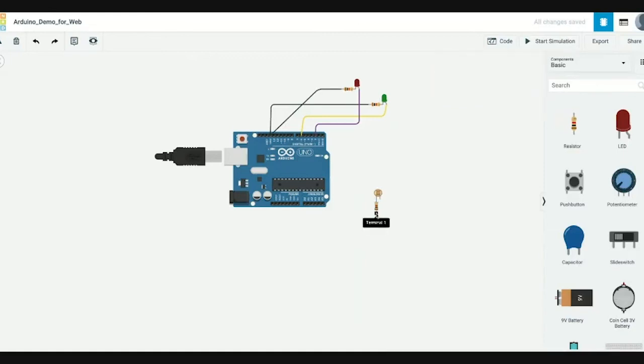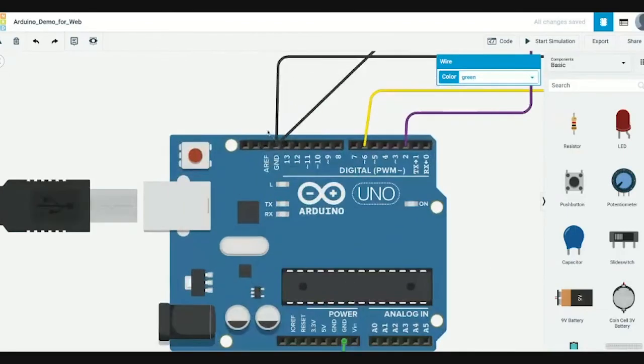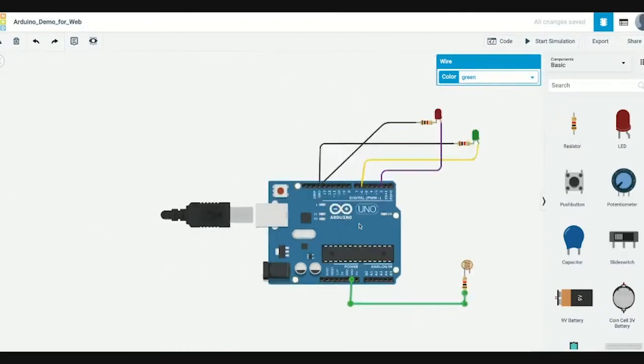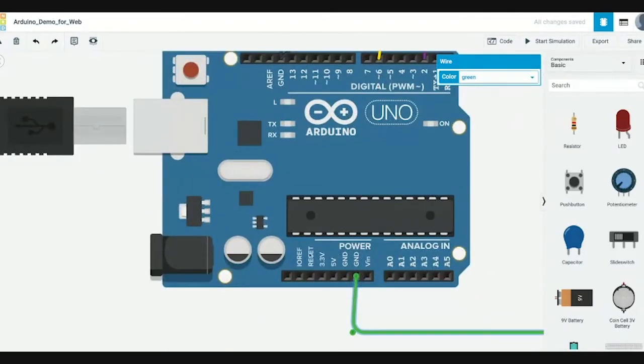You can connect these components together, just connect the resistor to one of the legs on the photocell. We are now going to connect from the resistor to ground, and notice how there are additional pins for ground on the microcontroller. In fact, there are 3 pins. We learned about the ground pin on the top of this board. There are also 2 ground pins on the bottom of the board, located here.